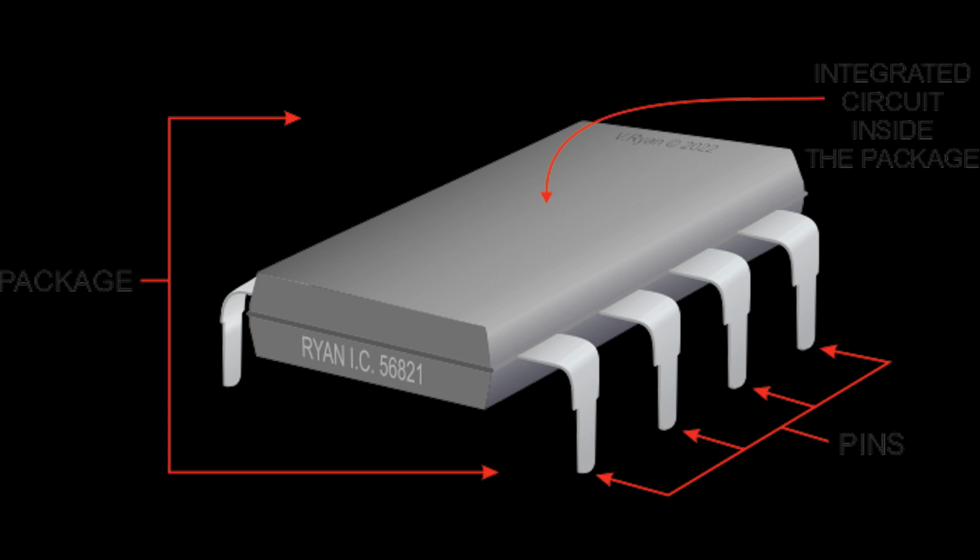2. Power supply sequencing. Function. Ensures that different power supplies within a system are powered up or down in a specific sequence. Prevents issues related to improper initialization and voltage levels during system startup. IC type. Power management ICs often include features for power supply sequencing.